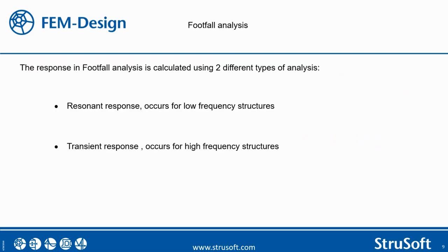The response factor for footfall analysis is calculated using two different types of analysis: resonance response and transient response. Resonant response occurs for low frequency structures. So in this case, if a structure has a relatively low stiffness, then the steady state is more significant, and the transient is negligible.